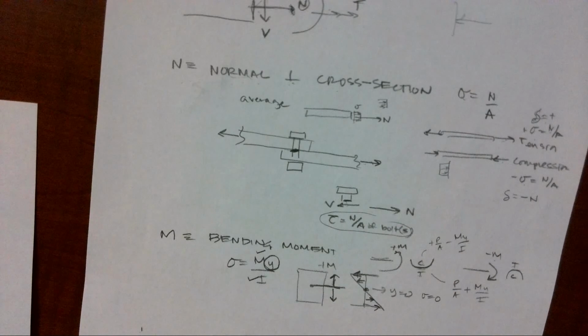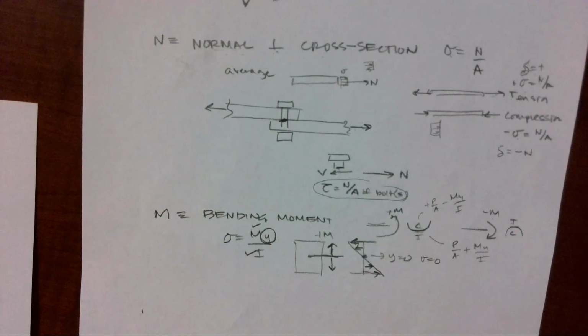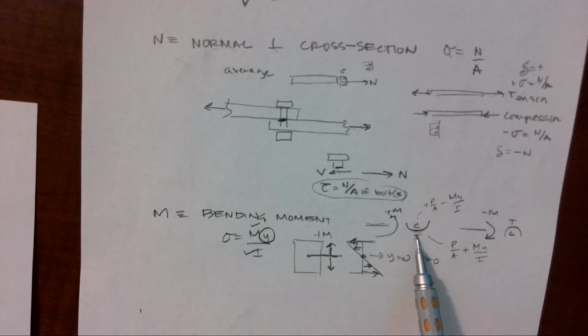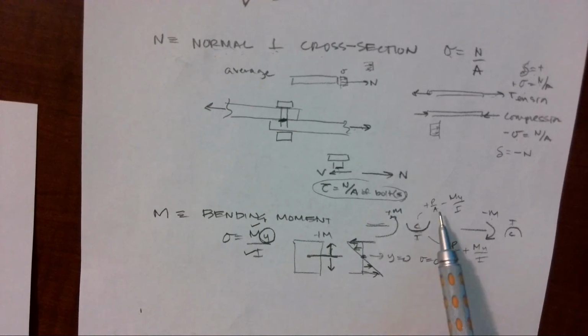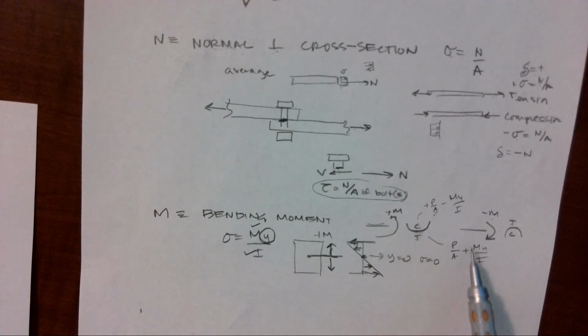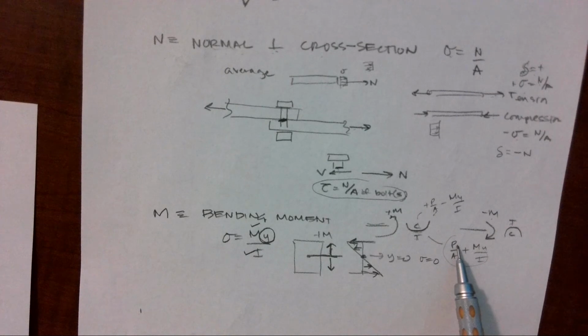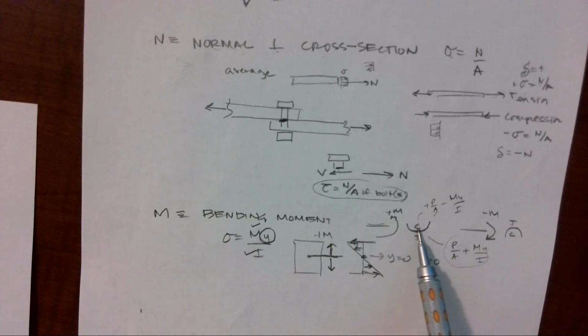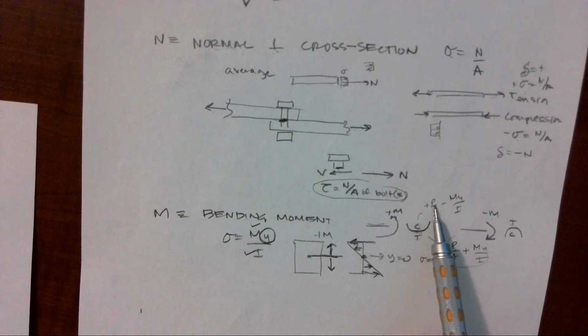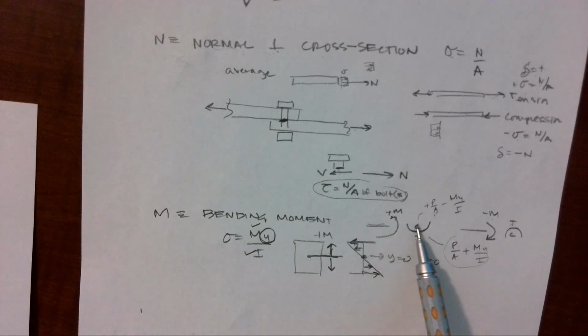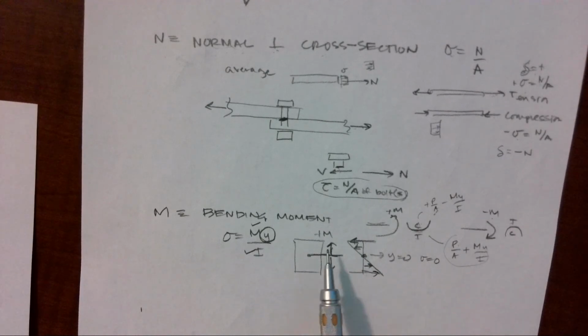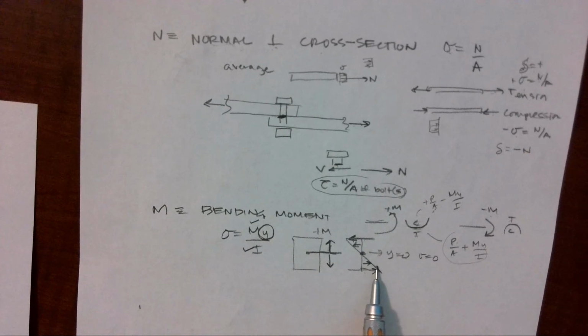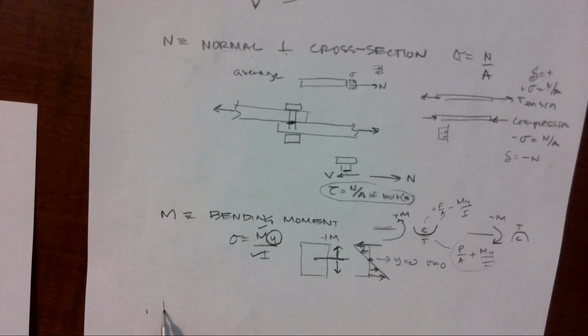And again, this is why it's super important to understand, am I working with a positive moment or a negative moment? What is happening? Because if I'm stretching to get around the curve and I'm stretching because I have a tensile force on there, then I'm actually increasing that normal stress. If I'm decreasing my length at the top to make that curve happen, but I still also have tension, it's not as much compression. So this could be shifted, but at the end of the day, it's always going to be linear. Okay, we've already done torque.